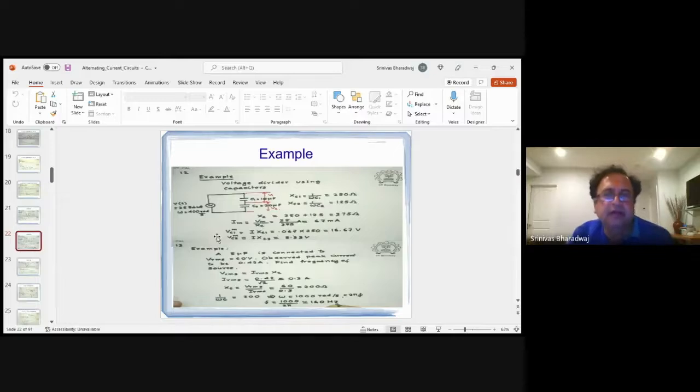So you write the current, and therefore once you know the current through the circuit, you can then find the V across each of them. The V across each of them is I times xc1, and the V across the second one is also I times xc2. Okay, think of xc as just like a resistor, only it has an imaginary component. Just think of it that way.